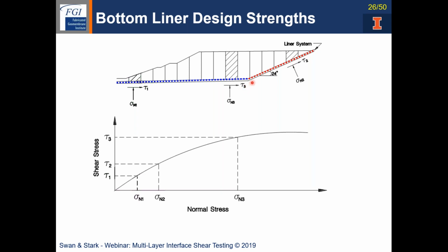So for those of you that aren't familiar with side slope and base, this is a cross section from one of the case histories. You would apply peak on the base for this blue dashed area. So there's not sufficient slope or shear stress to induce detrimental shear displacements and move you from peak to residual under static conditions.